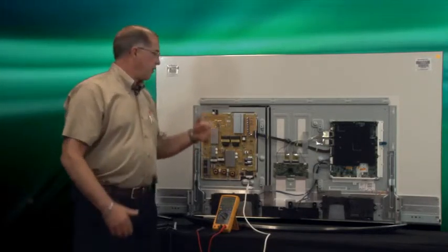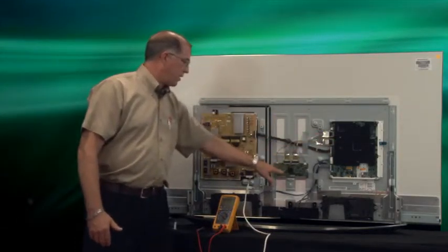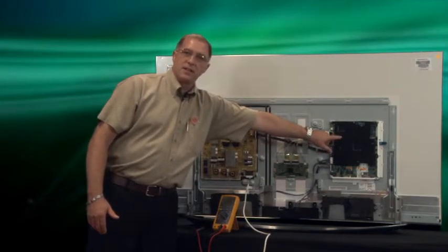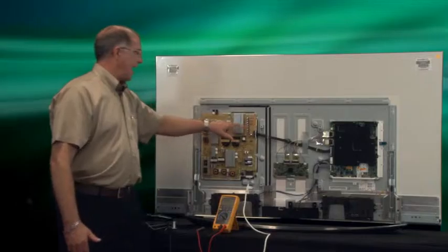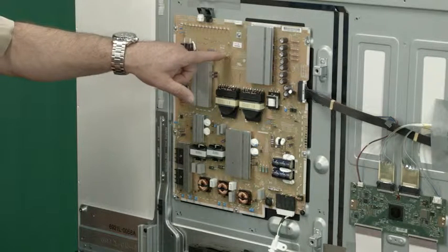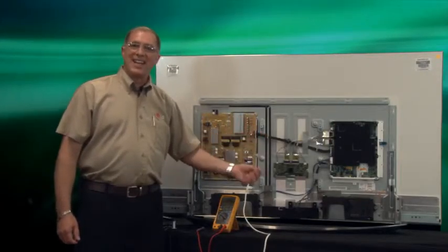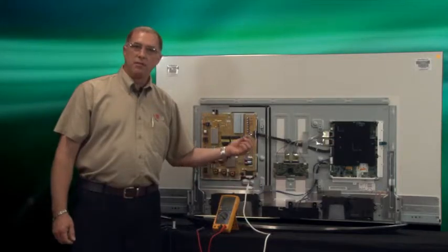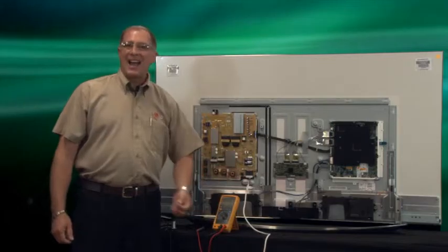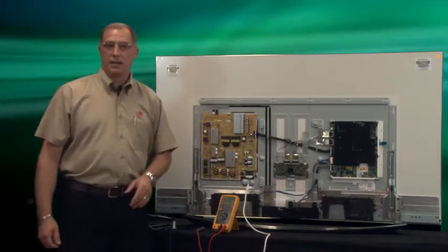As I mentioned earlier about dimming information, your dimming information is coming out of the main board or it can come out of the inverter. A lot of the new 2015s, it's coming out of the main board. Absence of PDIM is going to cause this LED to blink, in this case, say 7 times. First thing you need to do is make sure you're getting dimming information from the main board.